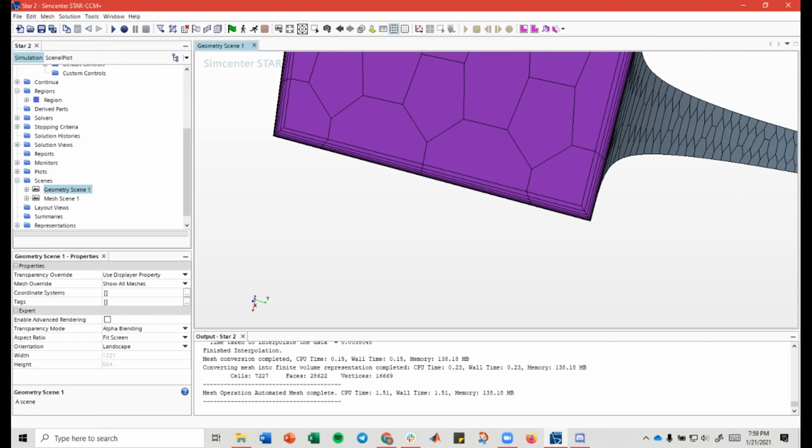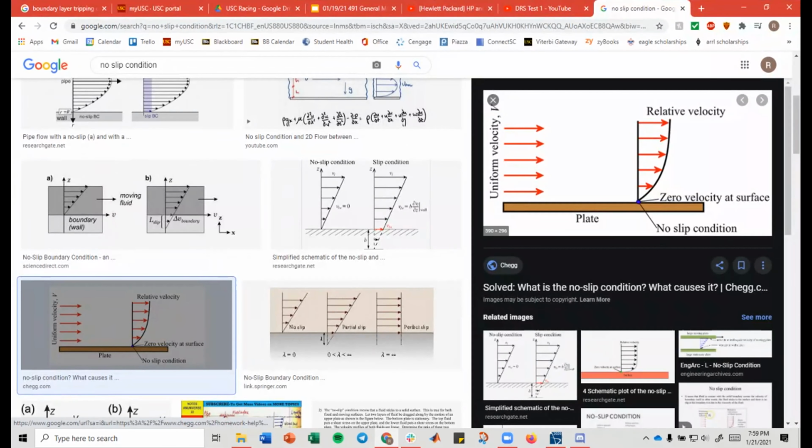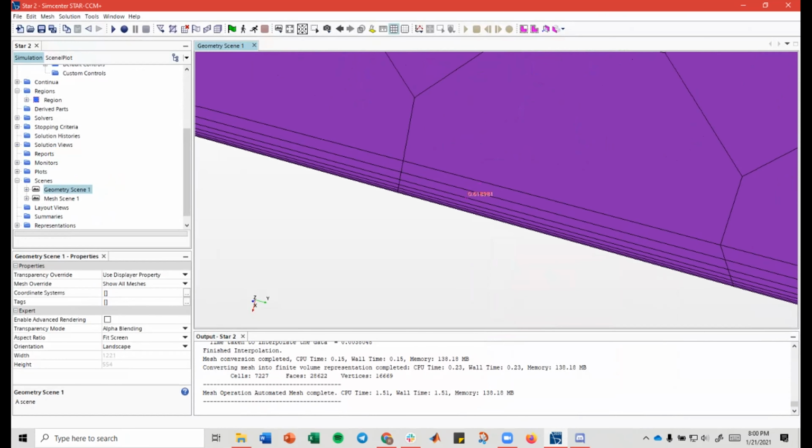And this is what we want because of that boundary layer condition, where the slope of that relative velocity curve is pretty high, in terms of x distance changing as a function of y. The velocity changes quicker as you move higher at the bottom than it does at the top, right? So that's why it's modeled like this.